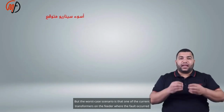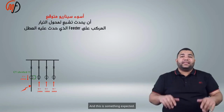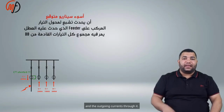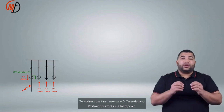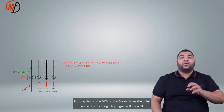But the worst case scenario is that one of the current transformers on the feeder where the fault occurred becomes saturated, and this is something expected because this feeder will carry the total of all the currents coming to it from the bus bar and the outgoing currents through it. We measure the differential and restraint currents, 6 kiloamperes. Plotting this on the differential curve shows the point above it, indicating a trip signal will open all circuit breakers.